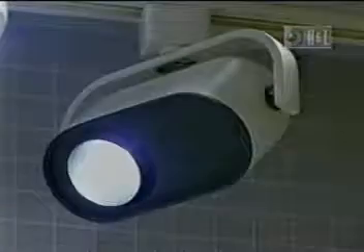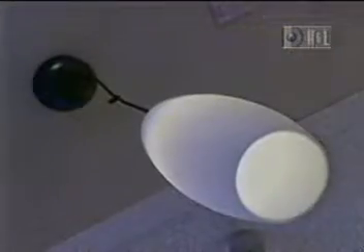Can you put dimmers on any of these lights, lamps? Lamps, right? Yes, you can. There are actually two different types of dimmers, a line voltage dimmer and a low voltage dimmer. A line voltage dimmer you can use for any lamp in the home. A low voltage dimmer you need for the pendants that you're installing. They're low voltage, so if you would like to dim those, you need a low voltage dimmer because of the transformer.